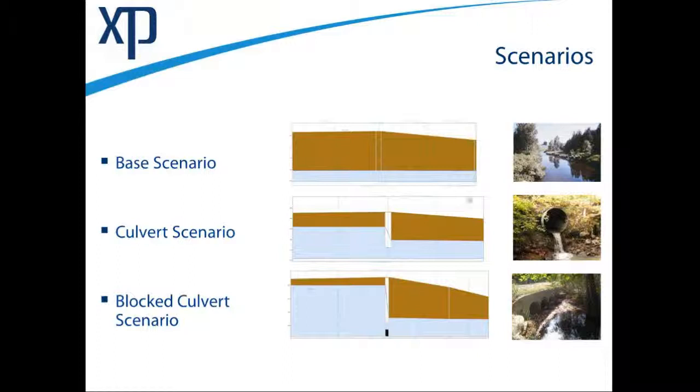Now, that blockage could be caused by the sedimentation, the debris that I've covered earlier, or maybe a lack of maintenance. So you may want to put in scenarios to say, if we do not regularly maintain the culvert, it could half block or three-quarter block or totally block, for example. So what we'll do, we'll look at the effects by integrating the 1D channel with the 2D. So we'll see those effects by illustrating the subsequent overland flood flow routes as a sort of fourth illustration.